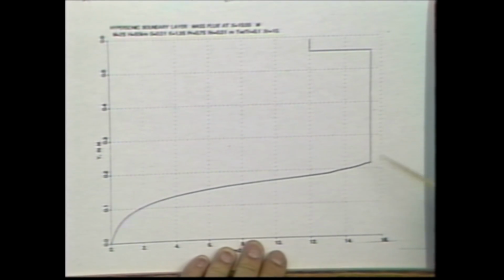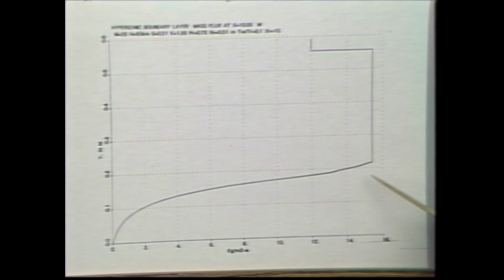The key thing I want to show you is, you notice the mass flux in the boundary layer is effectively 0. There's almost no mass flux here. This looks like a corner in the profile. In fact, it's not. If I plotted this on a larger scale, you'd see that this is continuous. It's just in the scale that I plotted it, it looks discontinuous. But that shows you the magnitude of the gradients associated with the boundary layer. The boundary layer in hypersonic flow is very sharply defined.